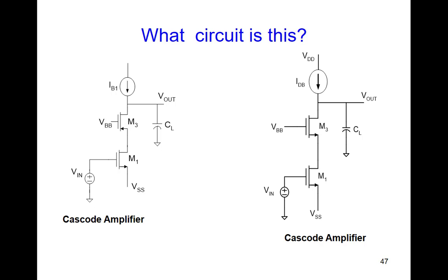So we would expect the characteristics, from a small signal viewpoint, we'd expect what? The same. Except we know intuitively the P channel has less mobility. So gains, okay, so numerically there may be some differences between the two, but keep in mind, we still are stuck with that P-channel device in the counterpart circuit. So here we get that nasty P-channel device in the quarter circuit, but it puts an N-channel device back in the counterpart circuit. Maybe that's not so bad. Yes. Okay?